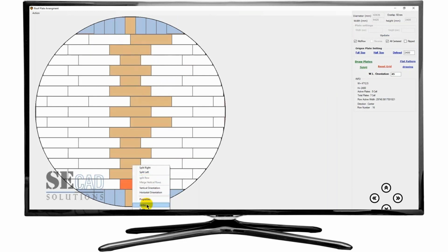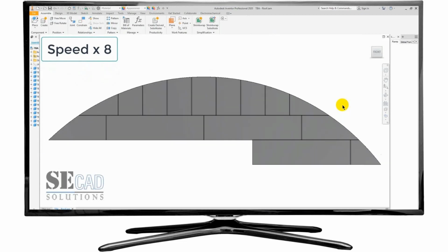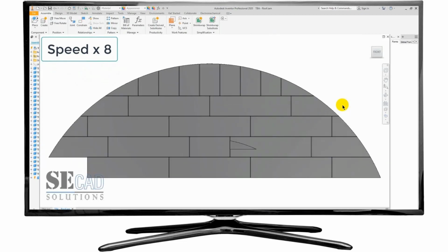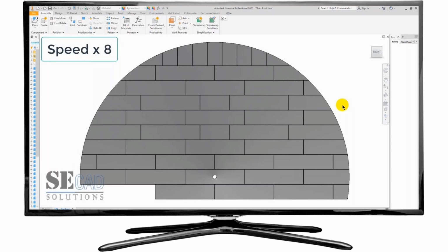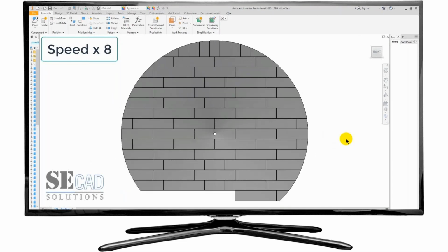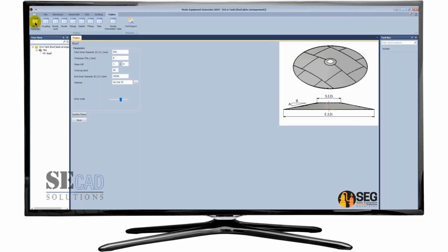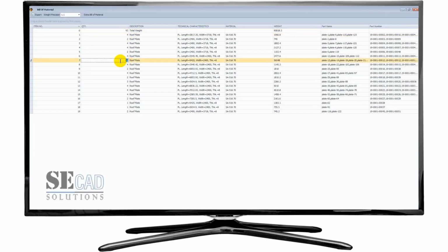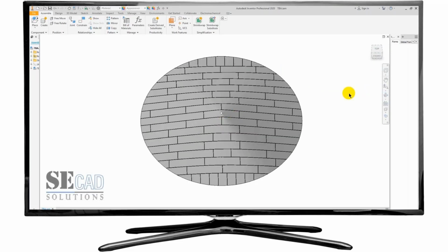Okay, here we can make the plate on the left side, right side. After saving, we will start creating the model on Autodesk Inventor. You can see that all data will be created automatically. The assembly will start automatically. Right here, you can see that all plates are assembled at one time. Okay, and in the bill of material, you can see all the bill of material for this roof with the definition of each plate and the weight of each plate will appear on your bill of material automatically.